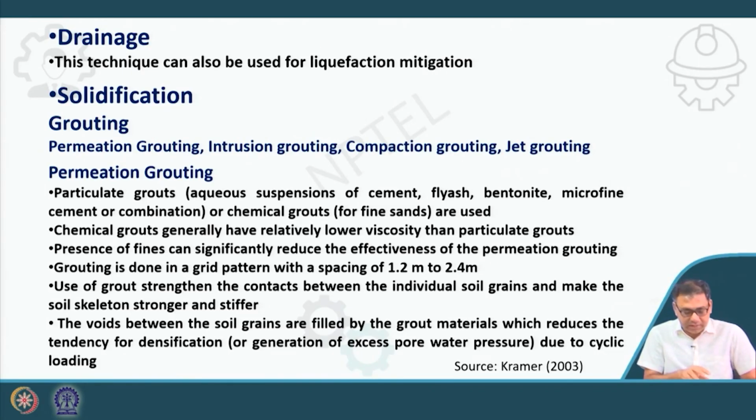For the solidification purpose we use permeation grouting and intrusion grouting, and jet grouting also, but that is under another heading, that is mixing. But compaction grouting is generally used for the compaction mechanism or densification purpose.